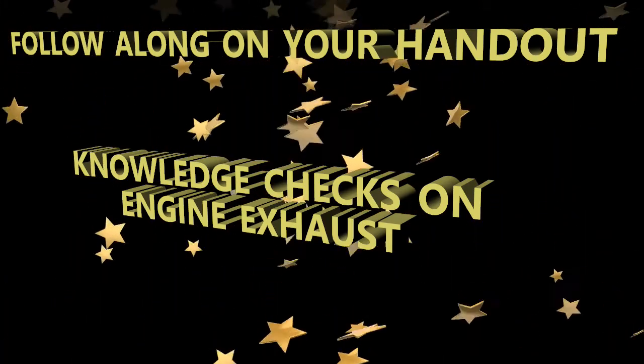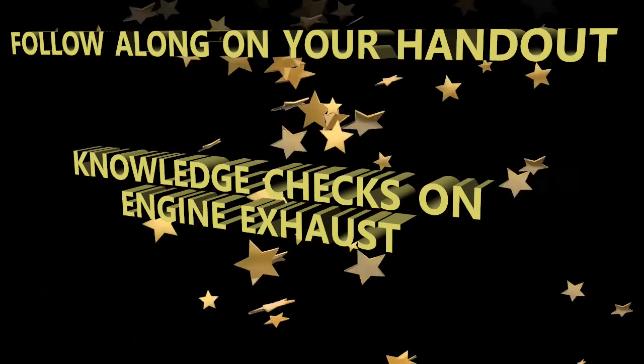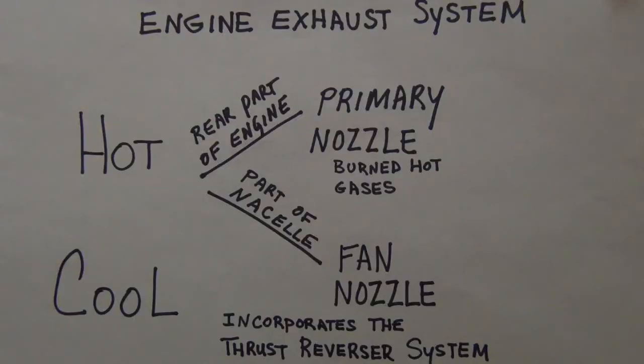All right. Now you've got to handle some of the questions here for this whole thing on thrust reverse. So we talked about the hydraulic actuators on the blocker doors. We don't need to go into great detail about that, the supply and return pressures to operate the actuators. Just know that they're there. There is a minimum hydraulic pressure to operate the latches so that you have a deployment. Okay, you had your stow and your deploy switches.